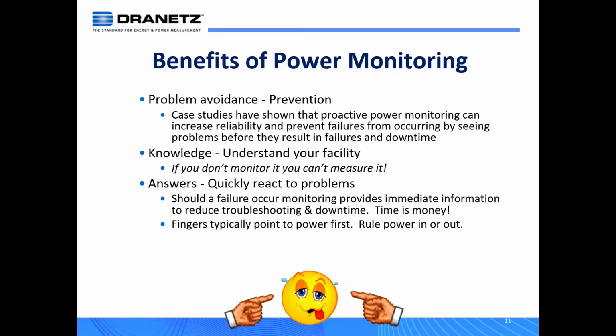So when you're proactively power monitoring, usually on a fixed basis, you can rewind that DVR and go look at this information. If you're not monitoring and you pull out one of our portable tools, like our HDPQ Plus, you're going to connect it, hope the problem happens again, and this time you'll capture it. So you're in effect using your systems as an alarm for your power problems. You don't want to necessarily be there if you don't have to. So being proactive can save you money, save you downtime, and prevent a lot of these problems from occurring potentially.